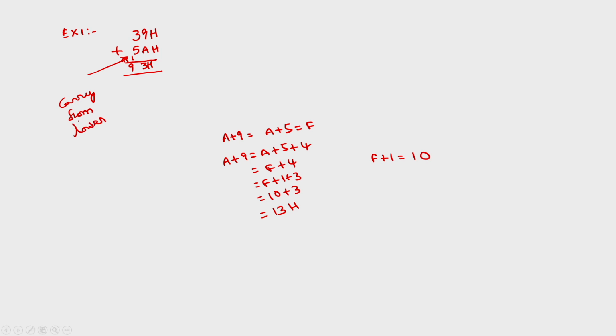This is lower nibble 9 and A. This implies the auxiliary carry flag is set. We can also check that there is no carry out of the MSB, so it implies the carry flag is reset. We can do this using binary also.